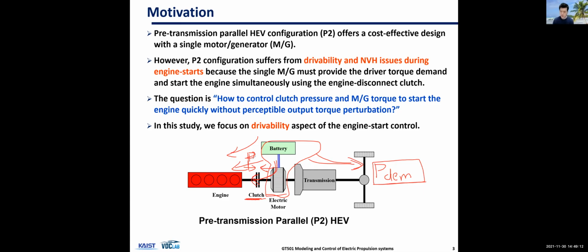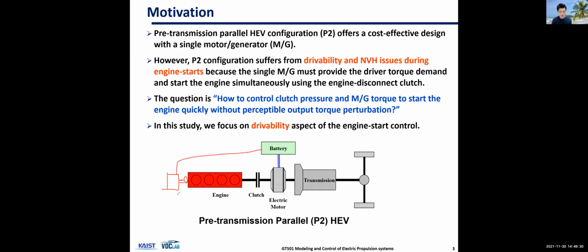So to mitigate this problem, Hyundai Motors actually put an extra motor here, so that they have a separate, dedicated motor generator, okay? So they can start the engine, which is motoring, right? If you want to start the engine, you need to motor. You have to put positive power into the engine. But then you can also use it as a generator.